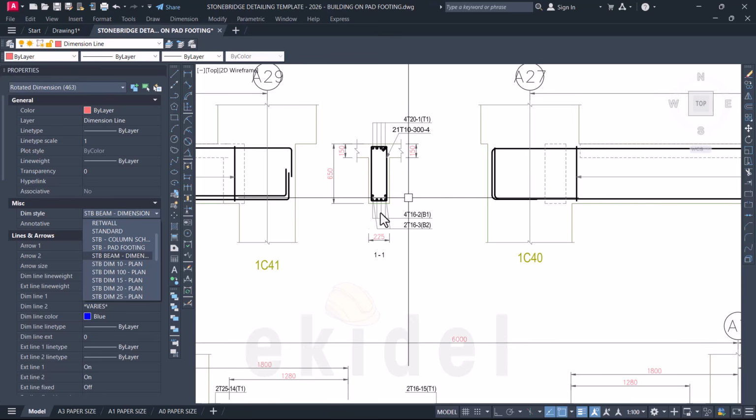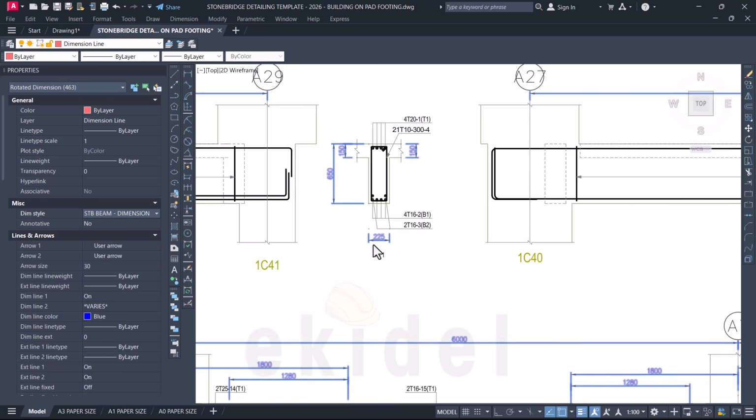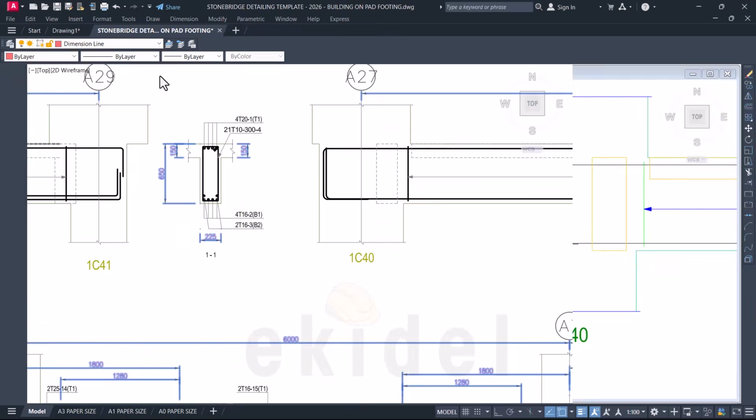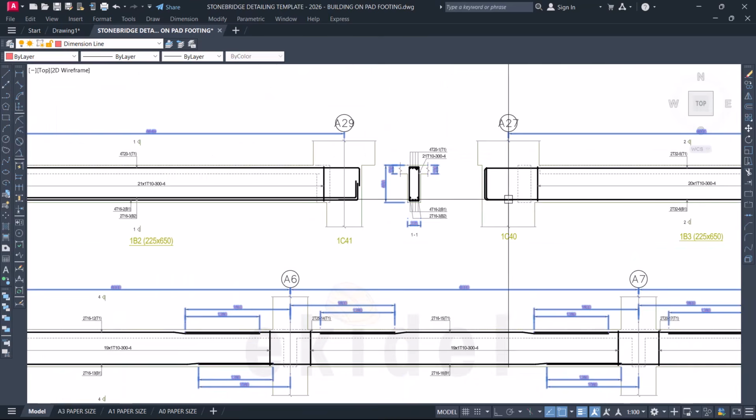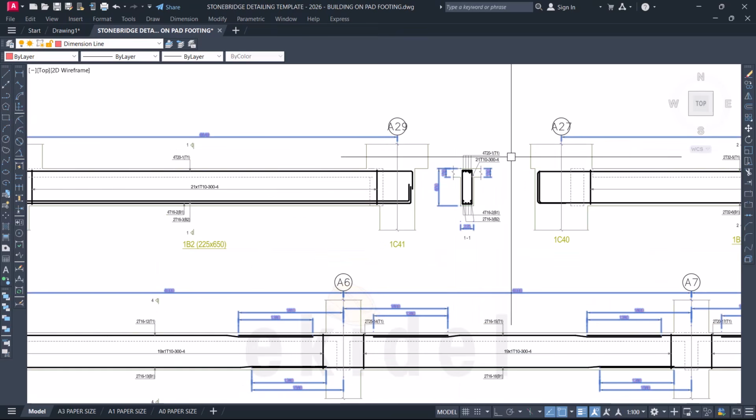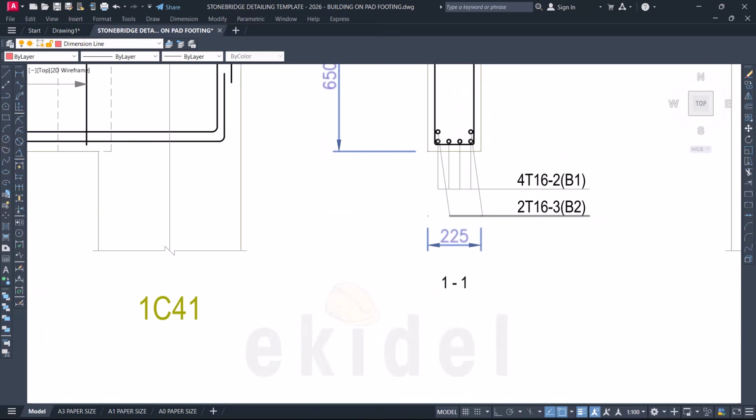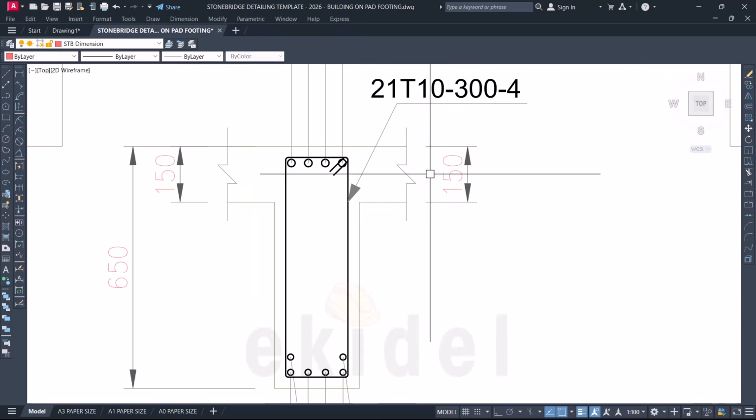Okay, that is fine, and you can see that the same size, the same dimension, is still the same. Now let's measure it manually just to confirm if our dimensions are still the same. That's why I say you should use the scale of 120, the scale of 25, when you're exporting from your Prota detail. Don't change the scale. So I'll now click escape. You can see that it has not changed the dimension.